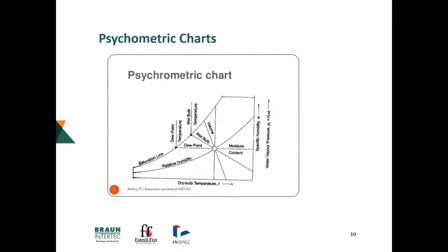So a psychrometric chart has this general form that we see here. Along the bottom, you take your dry bulb temperature, which is essentially your interior temp, run vertically till you hit that little round spot, which is intersecting with the relative humidity curves, and there are several of these curves that you'll see in the next image. And then you go directly left horizontally until you hit the outside saturation line, and that is your dew point.